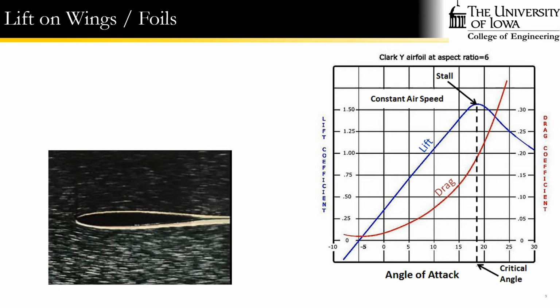Another way that this problem could have been framed is I could have said, here's the speed of the aircraft, here's the weight of the aircraft. Find the lift coefficient and find the angle of attack. In that case, you would have found the lift coefficient by saying our total weight of the aircraft is about 1/2 rho u squared times area. You would have said, maybe that lift coefficient is 0.5. Bam. What's the angle of attack for that lift coefficient? Right around 2 degrees. What's the drag coefficient at that point? Maybe about 0.03.